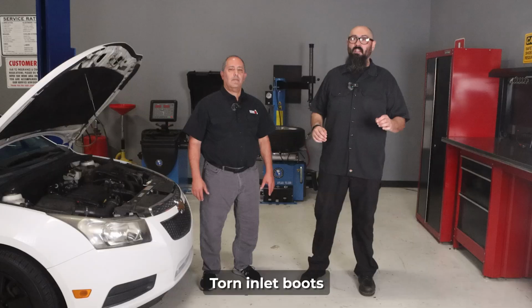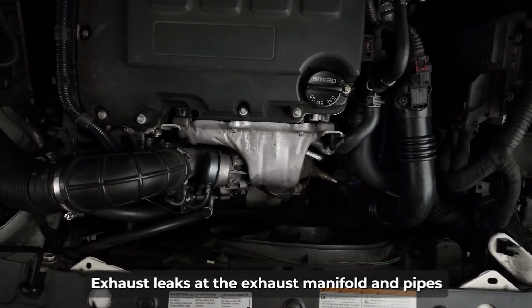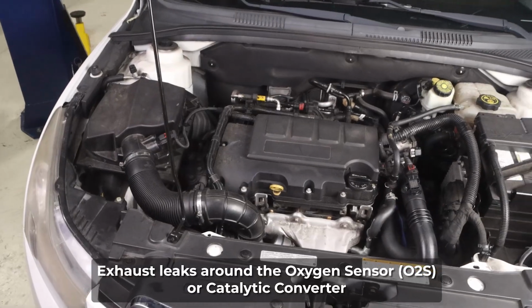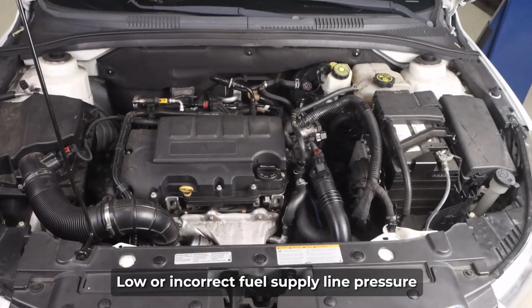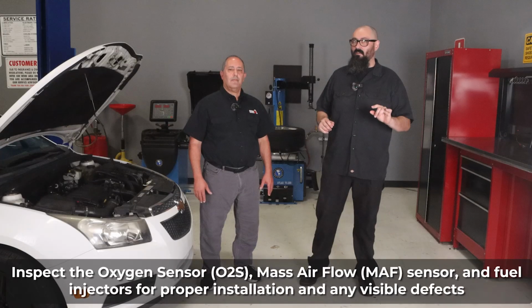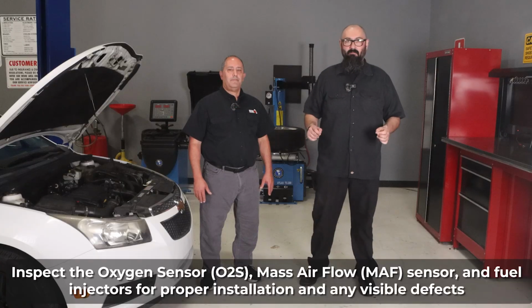Now, after gathering that information, perform an initial inspection for any obvious mechanical issues such as torn inlet boots, missing or broken vacuum tees, exhaust leaks at the exhaust manifold and pipes, exhaust leaks around the oxygen sensor or catalytic converter. You also want to check for low or incorrect fuel supply, possible vacuum leaks, and inspect the oxygen sensor, mass airflow sensor, or any obvious visible defects. Next, refer to the service manual or any applicable TSP for any additional diagnostic information before you continue. Now that that's done, we can go ahead and scan for codes and continue the investigation.